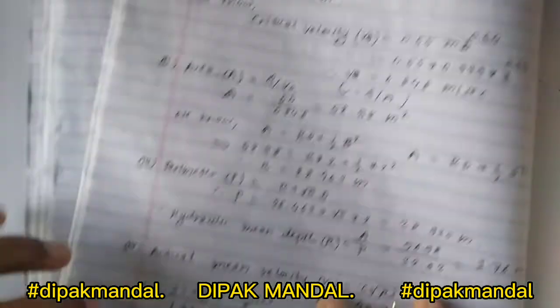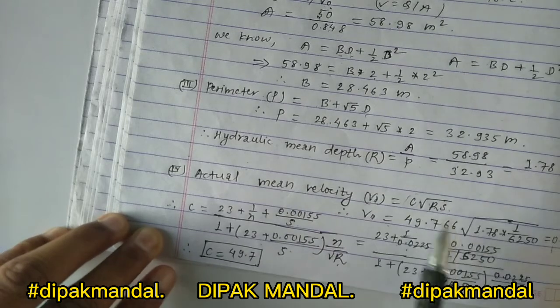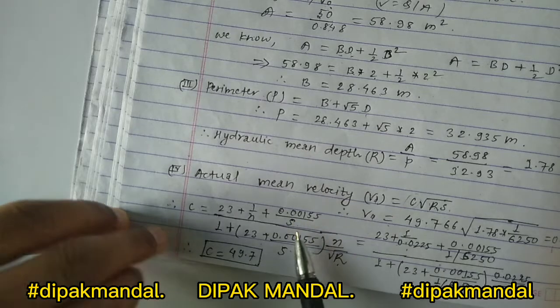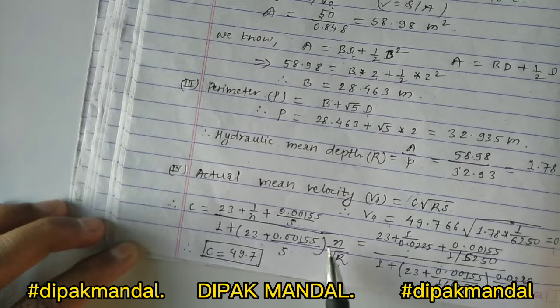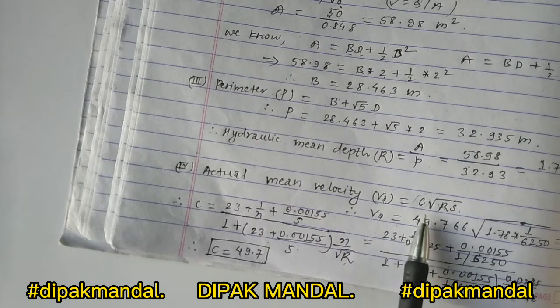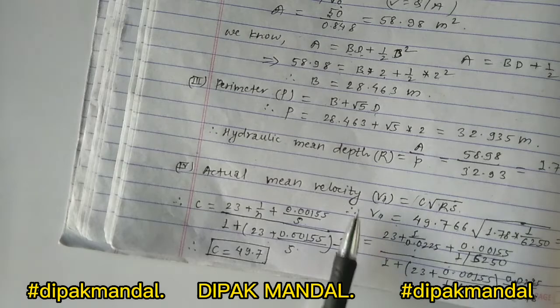Okay, so we have the value of C, as we said, actual mean velocity V equal to C root under RS, and the value of C equal to 23 plus 1 by eta plus 0.00155 by S, divided by 1 plus (23 plus 0.00155 by S) into eta by root over R. Okay, so this is determining the constant, that is the value of C, in the equation of actual mean velocity, that is Va.